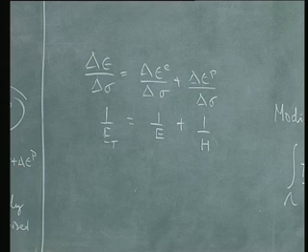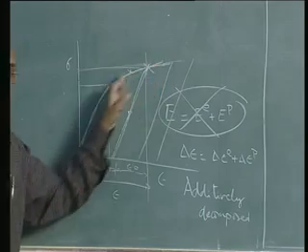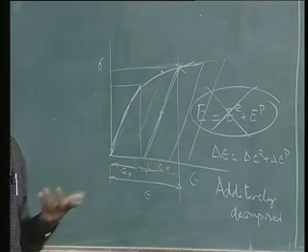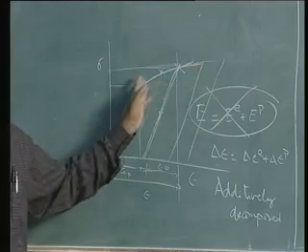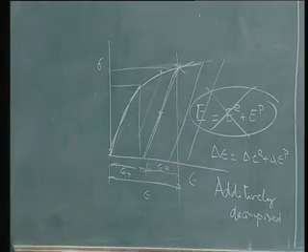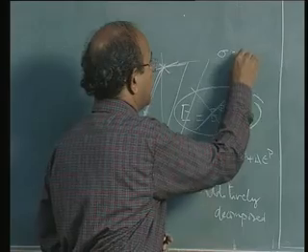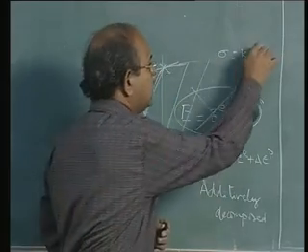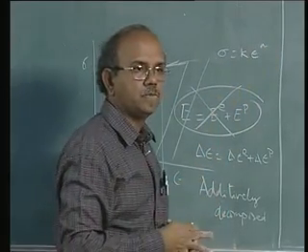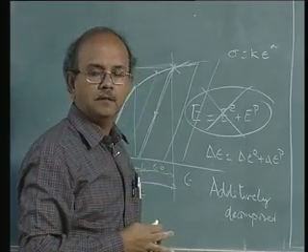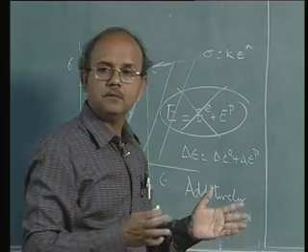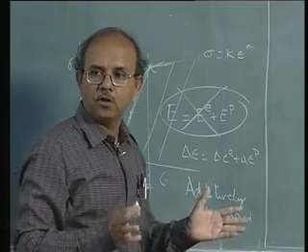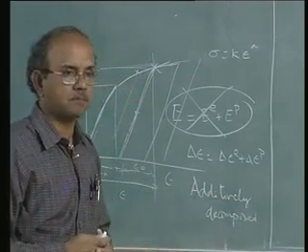That is dictated by the curve here. If it happens to be bilinear, then I'll have only 2 values. If the curve is a nonlinear curve expressed, for example, in terms of sigma equals k epsilon power n or something like that, then d sigma by d epsilon would not be the same. Is that clear? It would not be the same for the analysis.